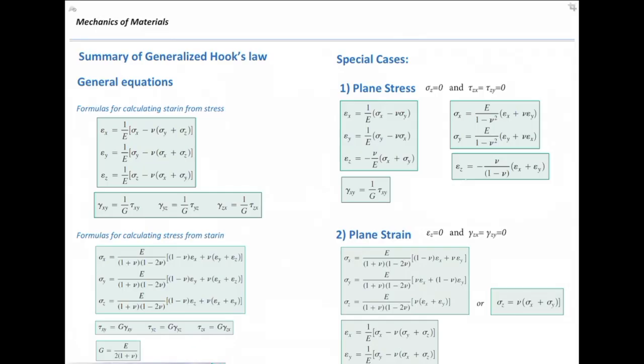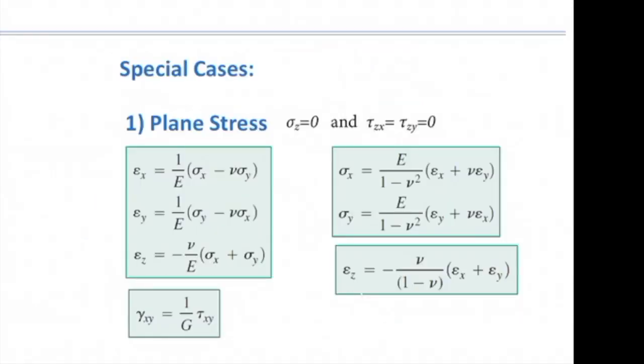We usually don't work with these equations. We usually work with the simplified case, which is plane stress, shown here on the top right. The equations on the left, epsilon x, epsilon y, epsilon z, give strain as a function of stress.